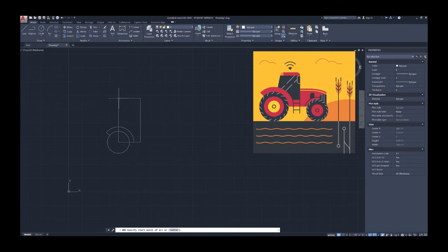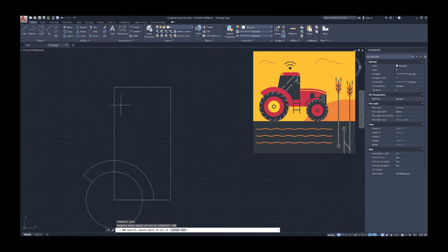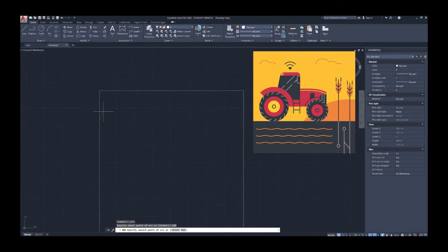You can actually specify, if you were to snap to the end point and drag your mouse, but you're not actually touching any button or anything like that, you'll get the X come up, okay? That's tracking where you are in the space, and it tells you that your extension is at 149.48, 270 degrees. Now, if I wanted my arc to start 100 mil down from that extension, I could type in 100, okay? And it would actually start 100 mil from where that endpoint is, which is pretty cool.